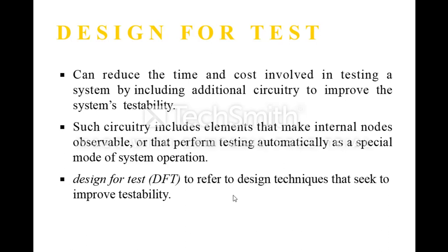The design for test can reduce the time and cost involved in testing a system by including additional circuitry to improve the system's testability. Such circuitry includes elements that make internal nodes observable or that perform testing automatically as a sequential mode of system operation.